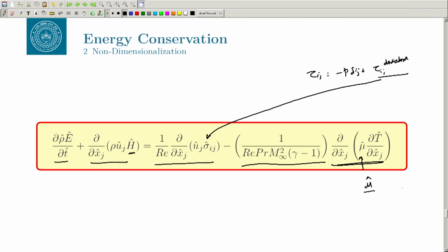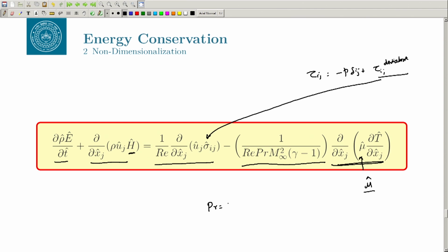and it works for most cases, because see the Prandtl number, the variation in Prandtl number is very small. Okay. So, your thermal conductivity may change with temperature, your viscosity may change with temperature, but the ratio between the two, which is nu by alpha, basically does not vary too much with the temperature. Okay. So, you can safely use the Prandtl number to be, I mean typically for air it is around 0.7 or 0.71. Okay. Although there are studies with the variation in the Prandtl number, okay, but for the normal cases at normal temperature variation, which is not very high, in those cases you can assume the Prandtl number to be constant. Okay.